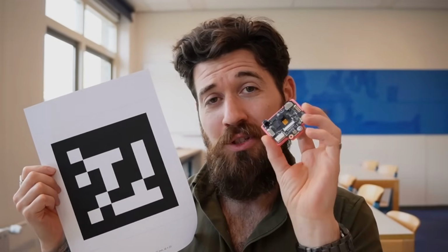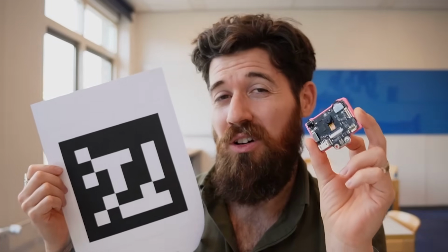What exactly is a fiduciary tag? And by a fiduciary tag, what is an AprilTag? So an AprilTag is this little grid here. It's an 8x8 square grid. And it is effectively kind of like a QR code for robotics, but it has less information in it. Now with a QR code, you have really dense images. Problem with really dense images with small camera sensors, it can be really hard to tell the difference between where one pixel starts and one pixel ends. So by actually having less data inside of one of these tags, we actually end up getting more data.